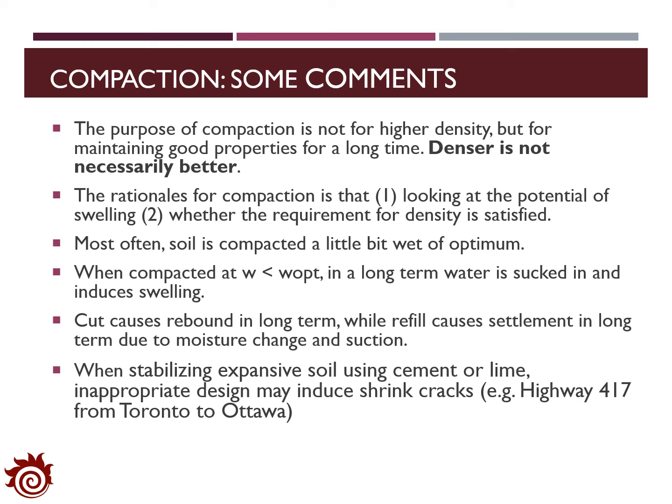For the subgrade design, we usually introduce a cut and a refill to handle the expansive soil. The cut will usually cause rebound in the long term, while the refill will generate a settlement in the long term. Both of them are caused by changes of the moisture content and the suction of water. If we want to introduce some stabilization of the expansive soil with cement and lime, then an inappropriate design may induce some shrinkage cracks for the road.